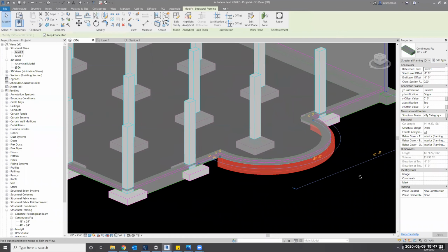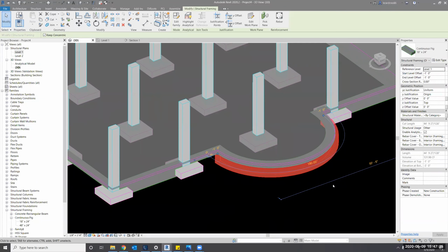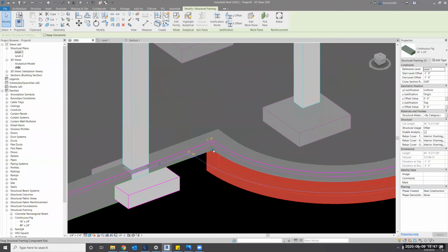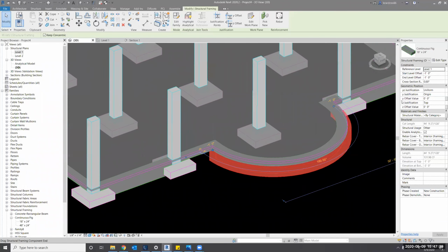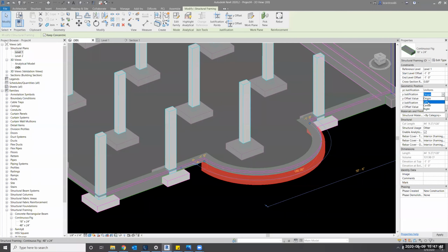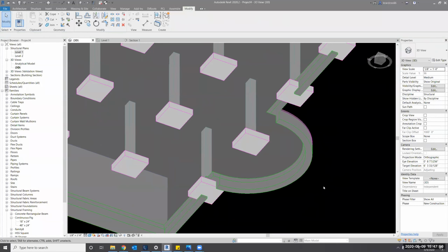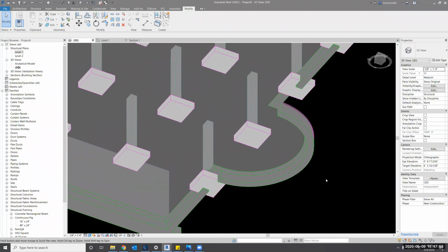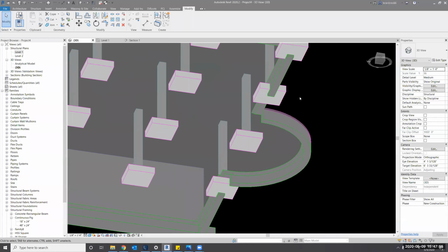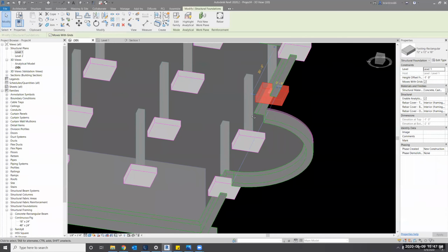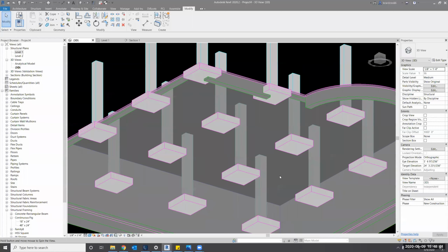Since this one is difficult to align, right? This is where it's nice to use this geometric position. So you see origin and top, you know, it wants to go, that top is the top center of this beam. So we can play with the Y now. So let's do left. All right, that didn't work. Let's do right. There you go. So now we have that turning under. Okay. Let's make these footings. Let's see here.